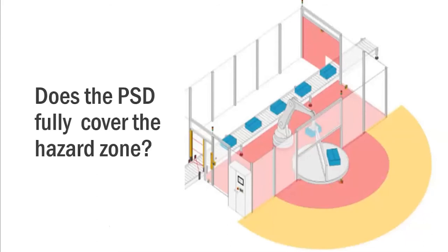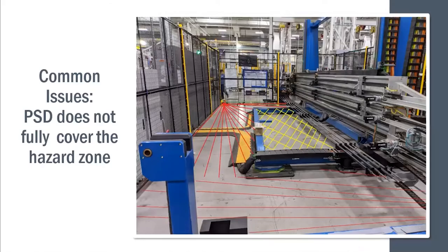So if we see these laser scanners in use, we want to see that they actually cover the entire hazard zone. Again, it's a direct line of sight to the beams, and are we covering the entire hazard zone? Here's an example. Here was an autonomously operating cell, and it was provided with two laser scanners, one here in the back, where I've drawn in the representative field that it's sensing, and another one in the bottom right corner, which is just out of view, and the field that it's sensing. And again, test the systems.